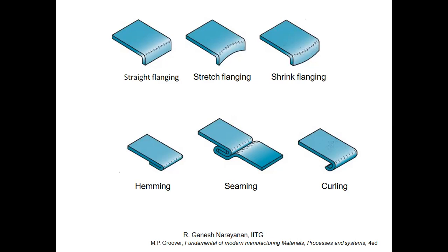As for shrink flanging, you have it outside, if you can observe, and therefore it would shrink. Here you're trying to stretch it because of that outward profile.